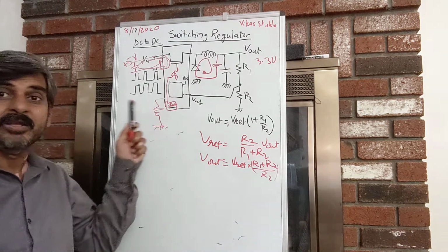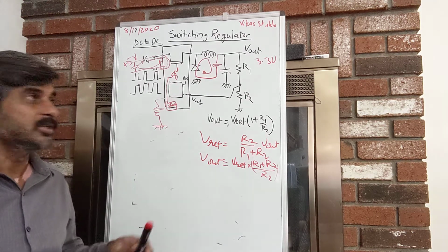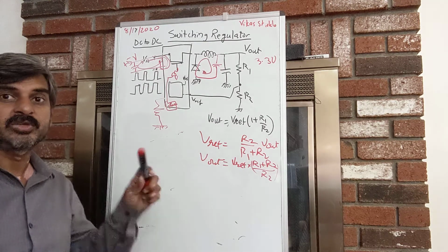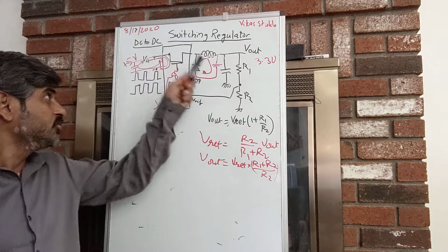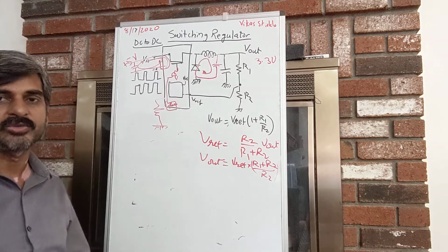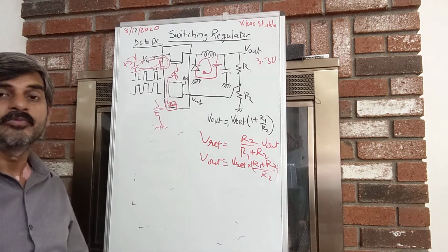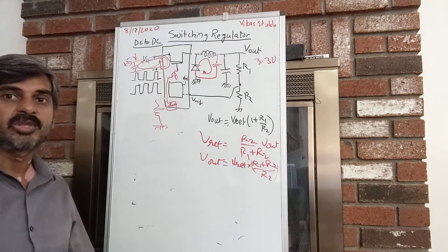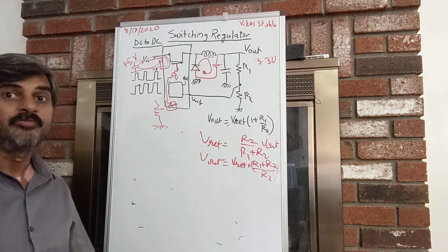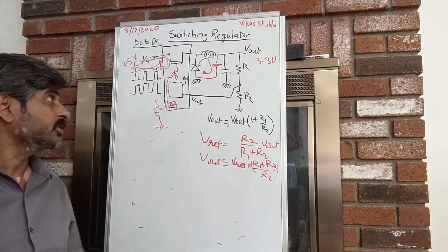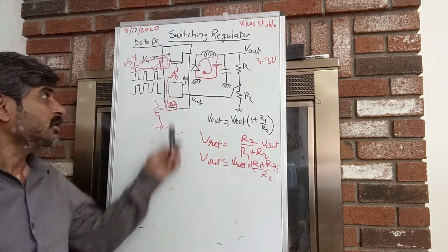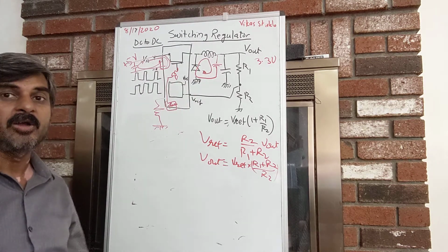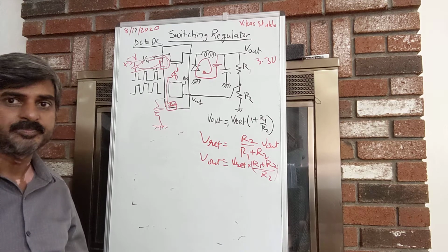But making it a higher frequency also creates the EMI problem, because now it's switching at a very high frequency, and you need to manage that high frequency noise. But if you can manage this noise and design it rightly, higher frequency is usually better. But if you think you could mess up the layout, not managing the return path on the input as well as the output, a lower frequency could be better.